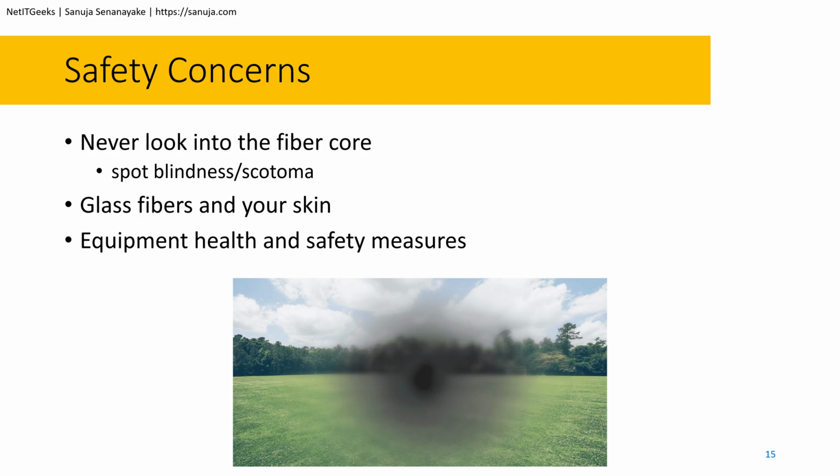You should never ever look into the cable. Even if your managers and supervisors tell you to look into it, do not do it, refuse it. It is illegal in Canada and the United States for any management personnel, team leaders or supervisors to ask you to look directly into the fiber cable, because it is a safety concern.